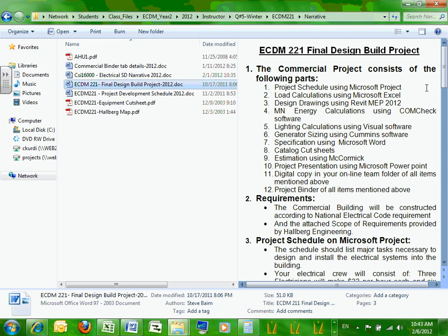So draw in Revit, in CAD, a box or a square that's 5 feet by 5 feet by 4 inches deep. That's the pad, call it pad. Trench, we trench at 24 inches, so we draw a trench like we did in the residential, at 24 inches to the top of the conduits. That's what we're going to give them.